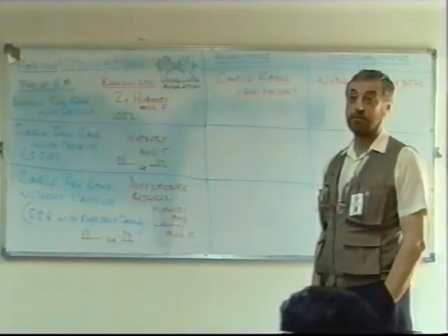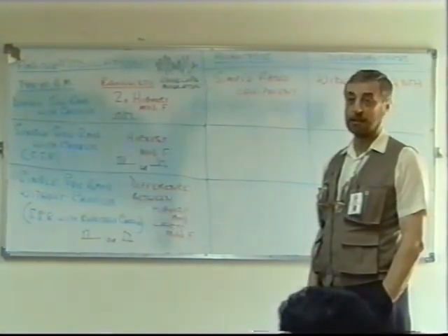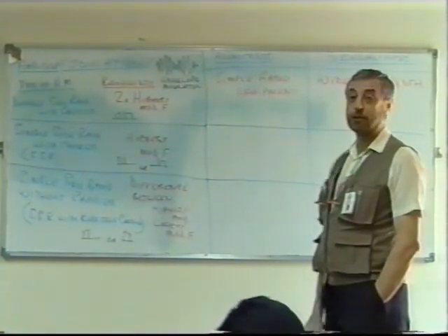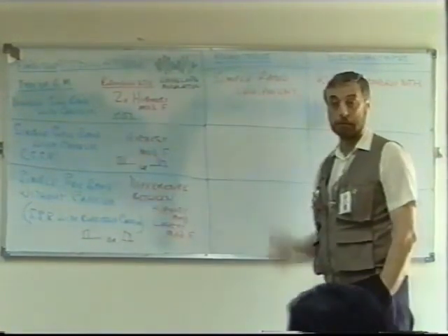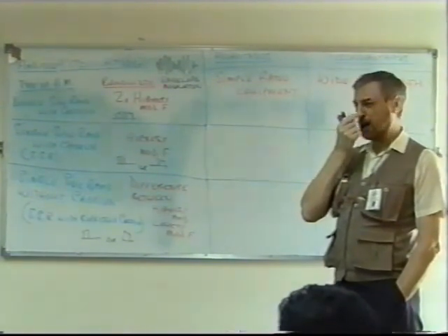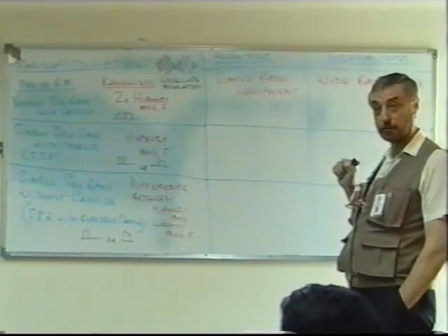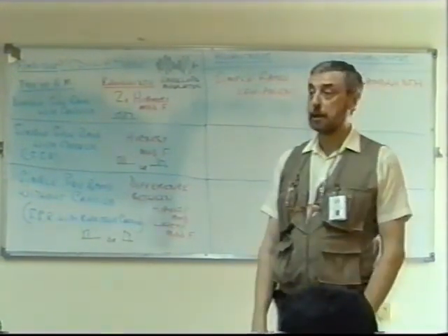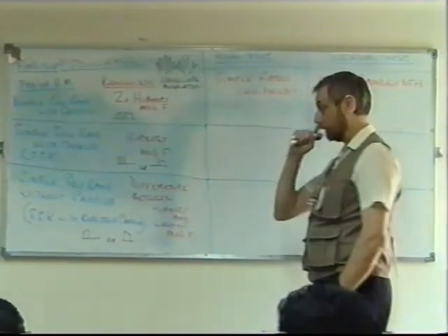Very simple. With a capacitor, yes, you need a capacitor to get rid of the RF, but the result is an audio output depending on the modulation. And it works very well. And a tuned circuit. Oh yes, I'm talking about just the demodulator now. You need the tuned circuit to receive your signal, tuned to the particular carrier you're talking about, if you're going to make the whole thing, yes, of course. But the demodulator is very simple radio equipment indeed.